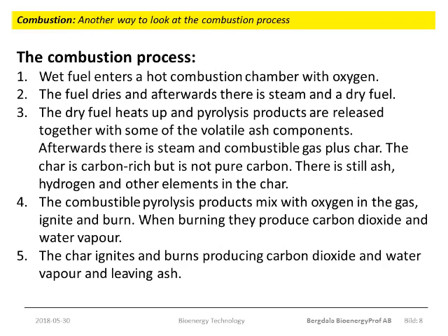As you learned in the previous lesson about thermochemical conversion, there is a process called pyrolysis. During pyrolysis, some of the solid biomass constituents are degraded and release a gaseous mixture of hydrocarbons and other gases when heated. As you will see in the Busy Plan Handbook appendix concerning fuel analysis, we call this fraction of the solid biomass volatiles. At combustion temperatures, the volatile components remain gaseous, but if cooled, at least some of them will condense and